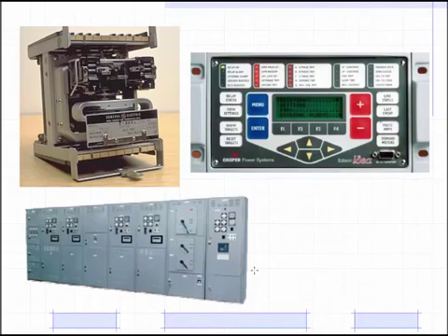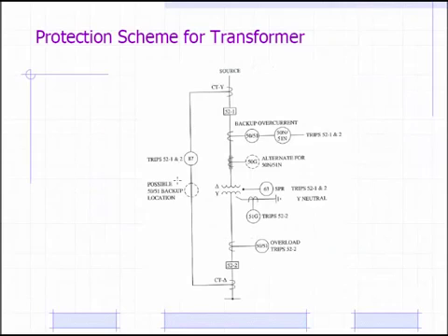Relays are the brains for breakers. They tell breakers when to trip. We've already looked a little bit at one-line diagrams. Here's a one-line diagram. 52, that's a circuit breaker. Here's a little CT going to a relay. A transformer, notice it's delta Y. Power goes down through another set of CTs, through another breaker, and on out.